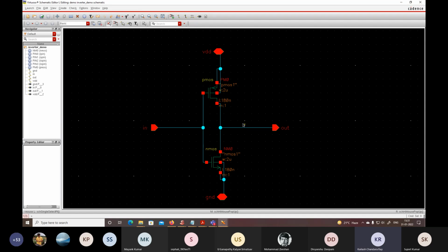If you look at the same drain current flow, if you look at IDP equal to IDN, then we will have mu n by mu p, then that will be your WP by LP over WN by LN. That should be 2 to 3 times.